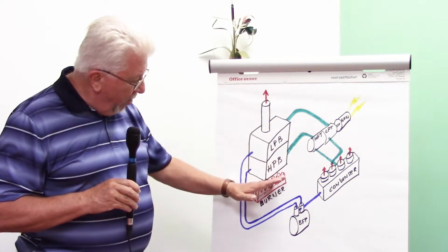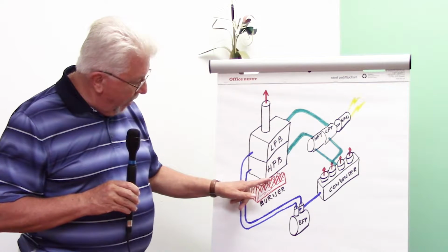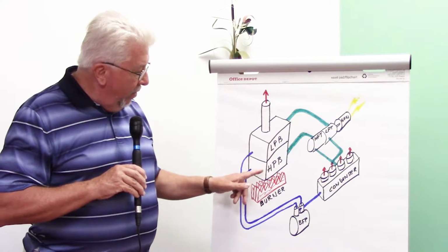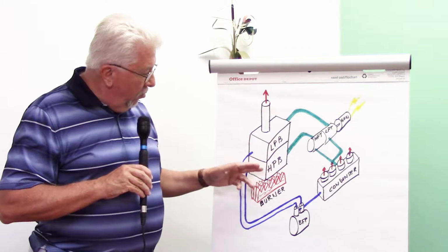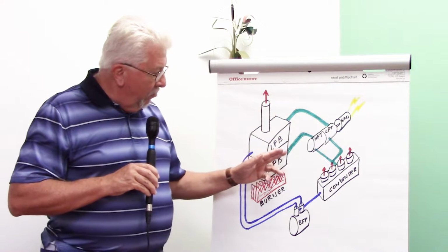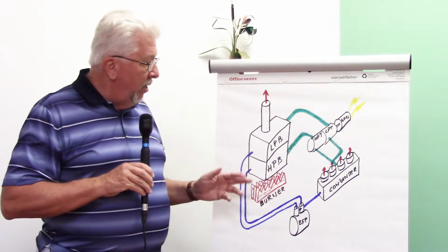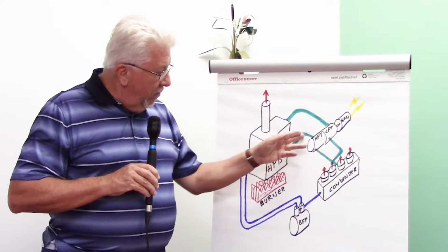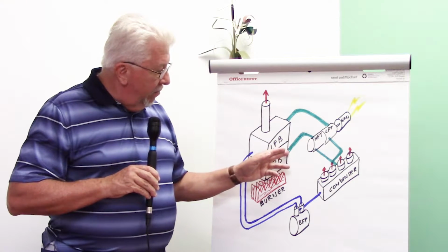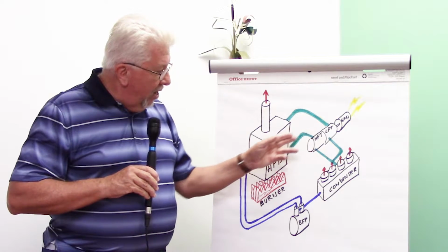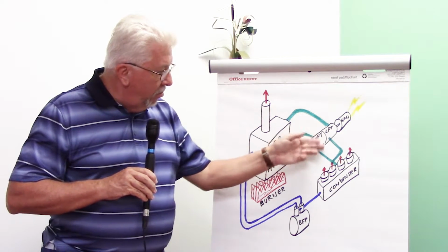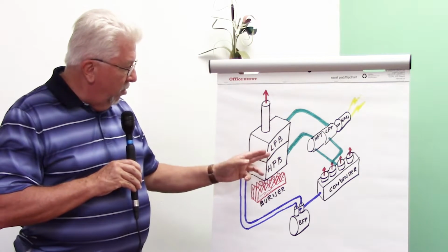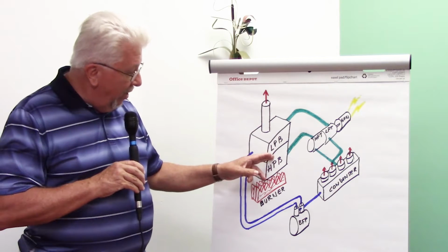They move through the boiler. They start off down here at around 2,500 degrees Fahrenheit. When they're exiting the boiler, they're exiting at around probably 1,300 degrees Fahrenheit. This boiler here converts liquid water into steam. That steam comes off of here, and that steam is around 1,100 degrees Fahrenheit, and it's around 1,000 psi. It's called a high-pressure turbine. So you have steam here that is around 1,100 degrees Fahrenheit, at about 1,000 psi, and it's pushing the turbine. The turbine turns. The generator generates electricity. Now the gases that are exiting here in the 12 to 1,300 degrees Fahrenheit range still have an awful lot of energy in them.